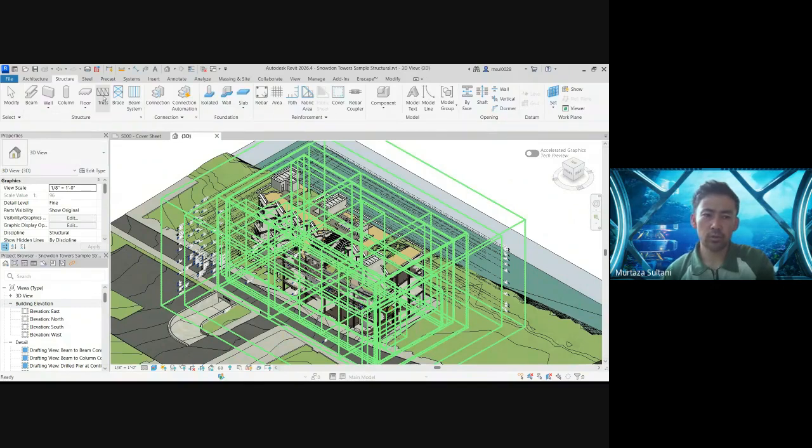You should be able to create various structural elements, edit their parameters, create and duplicate them, transfer them from one project to another, and define different reinforcement numbers.